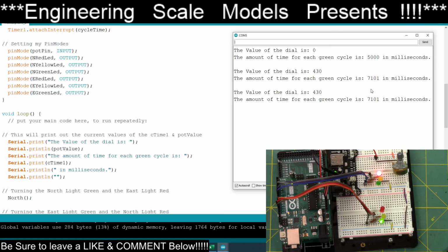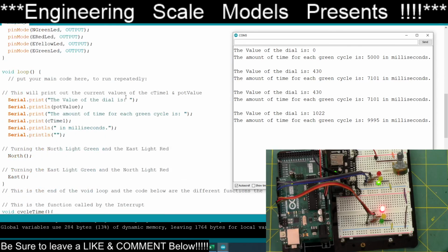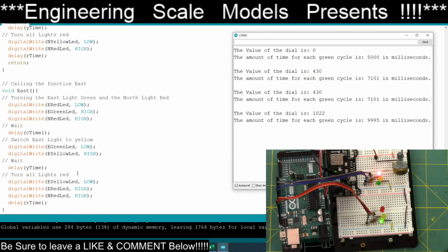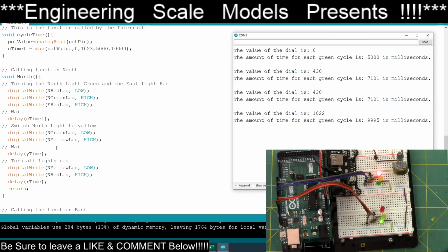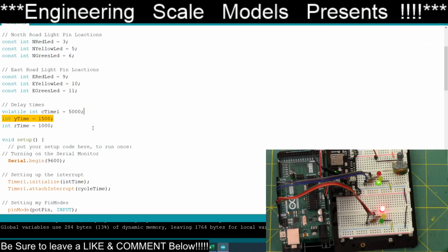Well, in this case, both cycles, but I have a more updated program that will update in more real time. It is reading the value of the potentiometer in real time through the interrupt. I'm just not printing it out in real time because you don't want to print from an interrupt. I'm not a fan of how I did these functions with all the wait times. So I created a different version using some loops that get in and out and update more effectively. So that's going to do it on software interrupts.